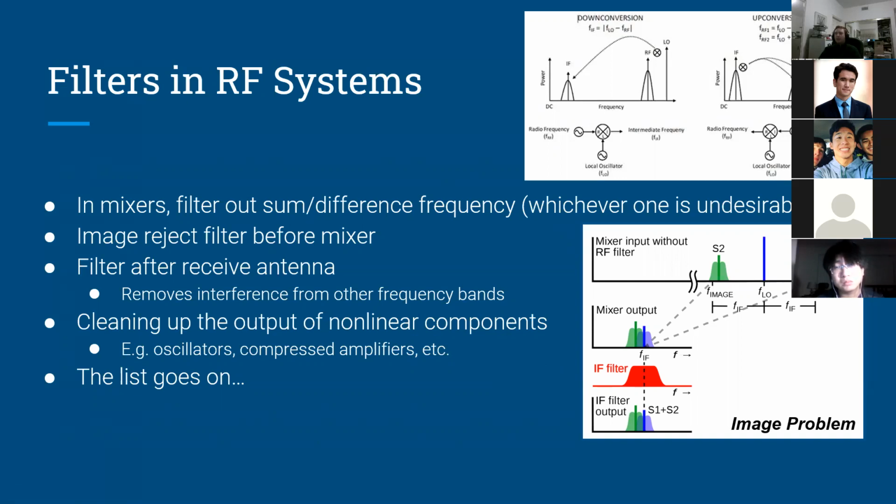So we have the 27 megahertz signal of interest. We have the 29 megahertz, which is the sum frequency. And we have the 28 megahertz, which is the LO leakage from the LO port to the output. Because LO isolation is not perfect, we're going to get some LO in the output. So we need to be able to filter out 27 megahertz from the 28 and the 29. And to do that, we could use a bandpass filter, and we'll see that shortly.